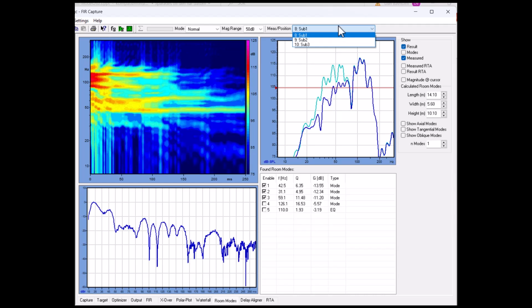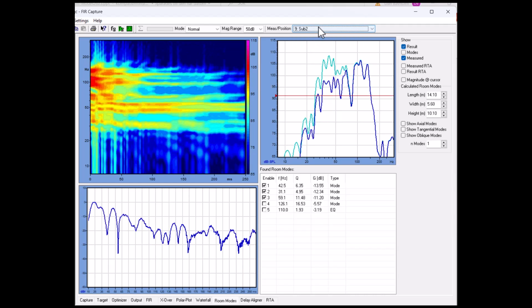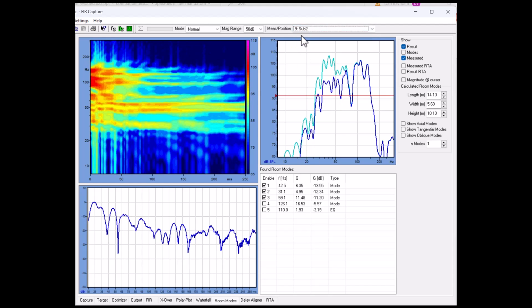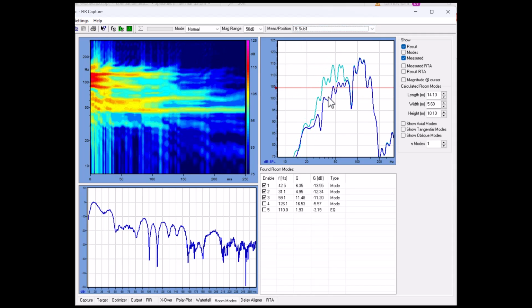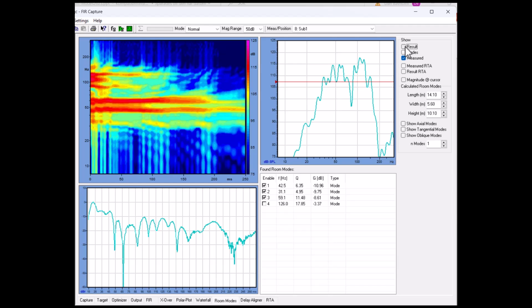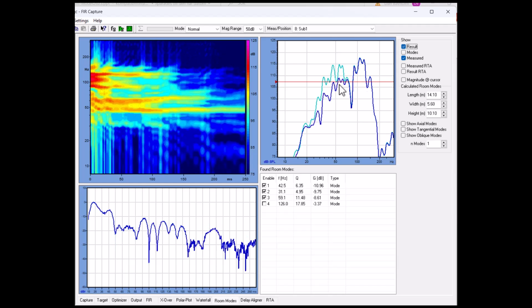And here you can see the different measurements and the room resonances are calculated, and here is a suggestion for filters to apply to the system. And of course this will improve the signal to noise ratio. And you can see here what happened with the ringing in the room. The result is that it will be eliminated.